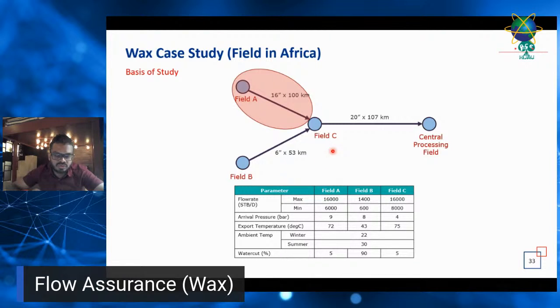They were also facing some water instability issue, because when they were pigging too frequently, there was a lot of fluctuation in production. There's a sudden water slug to this particular field for every pigging activity. So there's a lot of instability of water flow that has caused a lot of production deferment as well.